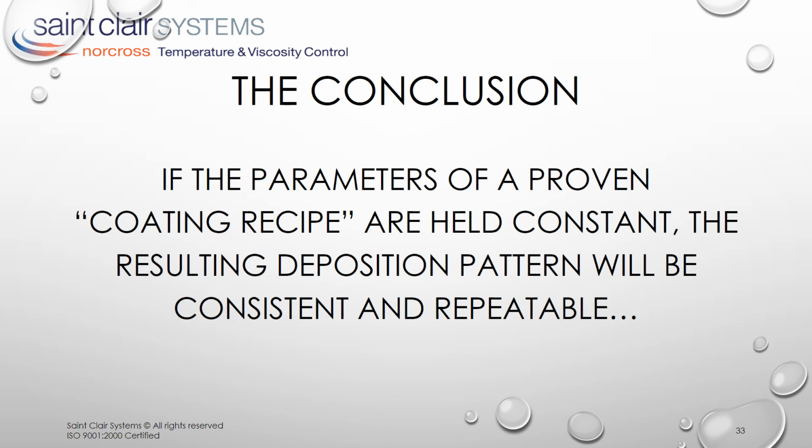This is especially advantageous where waterborne or 100% solid coating formulations can be substituted for more conventional solvent-borne versions to gain significant performance and/or environmental benefits without incurring major rework, downtime, and cost in the implementation. In each case, temperature variations result in viscosity variations that undermine those advantages. In fact, these newer, more modern coating formulations are often even more temperature sensitive than their older counterparts.